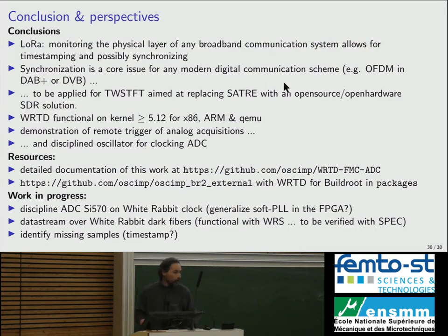And with that, I conclude my presentation summarizing what we did. So we tried to investigate LoRa communication for time and frequency dissemination. We've seen that LoRa is a narrowband protocol, only 8 microsecond time accuracy. So you don't expect to have high resolution, but maybe that's enough if you want to do something like replacing DCF77 or TDF. We've seen how you can use the low-level hardware protocol to identify time of flight and frequency.